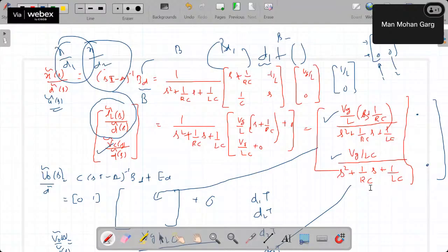Sir, for multi-input systems, how can the inverse matrix be solved? Okay, madam, for the inverse matrix the procedure remains the same. The only thing is how to obtain the A, right? Obtaining A will depend upon the number of energy storage elements. The size of A depends upon the order of the system. So if you are able to write the basic equations for each mode and average them, you'll get the A. And A is called the system matrix, and that is the only one required for inverse. For the other matrices no inverse is required. They are just addition or subtraction only.